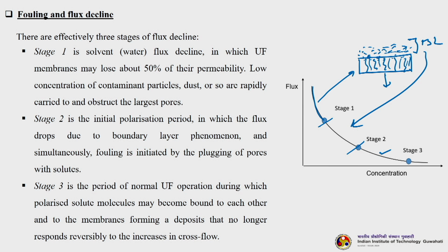In which the polarized solute molecules may become bound to each other and to the membranes, forming deposits that no longer respond reversibly to the increasing crossflow. That means, what is happening? This is strong interaction between solute and solute, so basically solute-solute interaction as well as solute-membrane interaction. Now, this interaction is becoming so rigid that if you increase your crossflow velocity very high, they are still not getting washed.